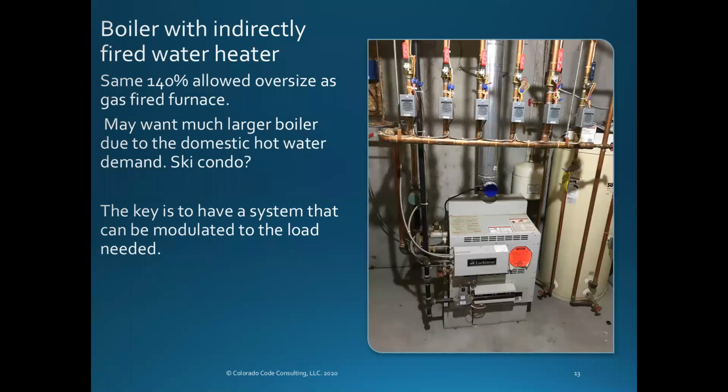Okay. Then we get into these ski condo things. We've run into a lot of stuff where you've got ski condo businesses where everybody's out during the day skiing and everybody wants to come back and they take 8 showers all at the same time, because they've got 14 bedrooms and several 3/4 baths and everybody's taking a shower at the same time. And of course they have to have what they call an indirectly fired water heater, and that's what this thing is over here. That's the water heater, and it just has a boiler loop, right? Coils inside there that heat the water.